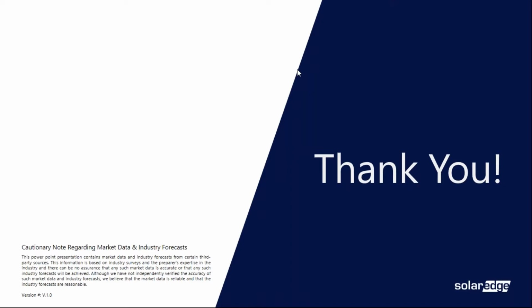Now, because SolarEdge has all that integrated into the backup interface, we don't suffer the same kind of requirements that the Tesla Gateway does. So if you're using a Tesla Gateway, great. It's a fantastic product. I'm a fan of it. All you have to do is use your PV inverter like you normally would. You're going to install the PV inverter into either the backup panel or the generation panel.